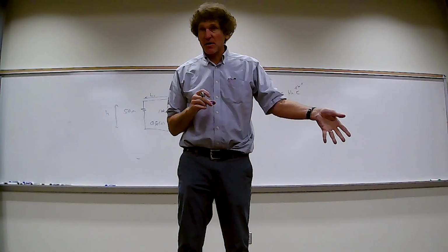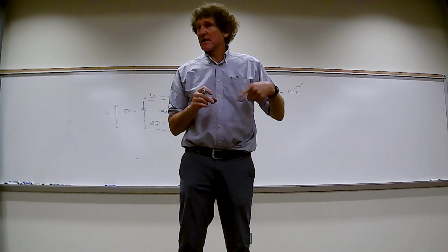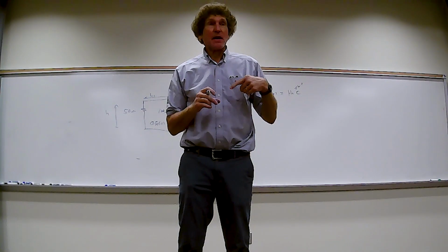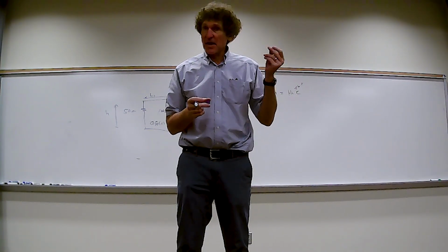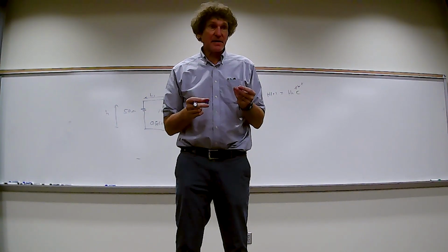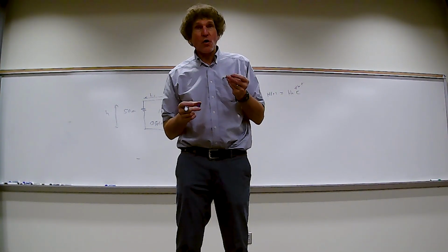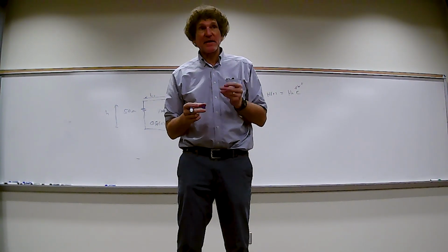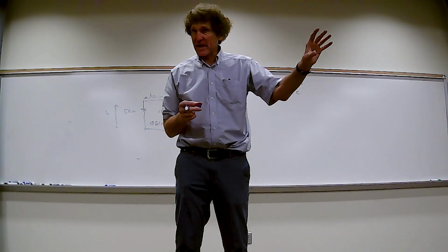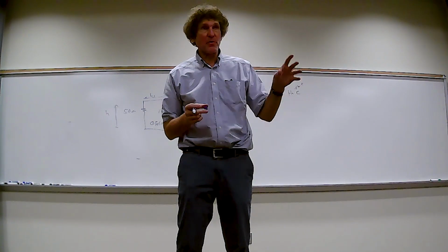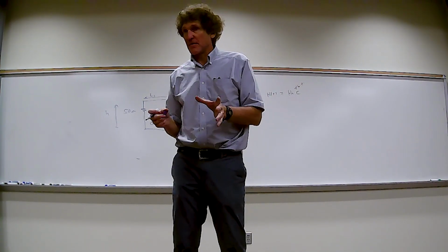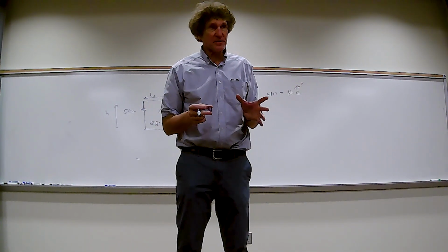Remember when you did circuits problems? For steady state circuits problems, everything varied as e to the j omega t, right? But at the end of the day, when you solved it for the time domain, you had to multiply by e to the j omega t and take the real part to get the actual time domain form. Do you remember doing this in Dr. Roman's class?